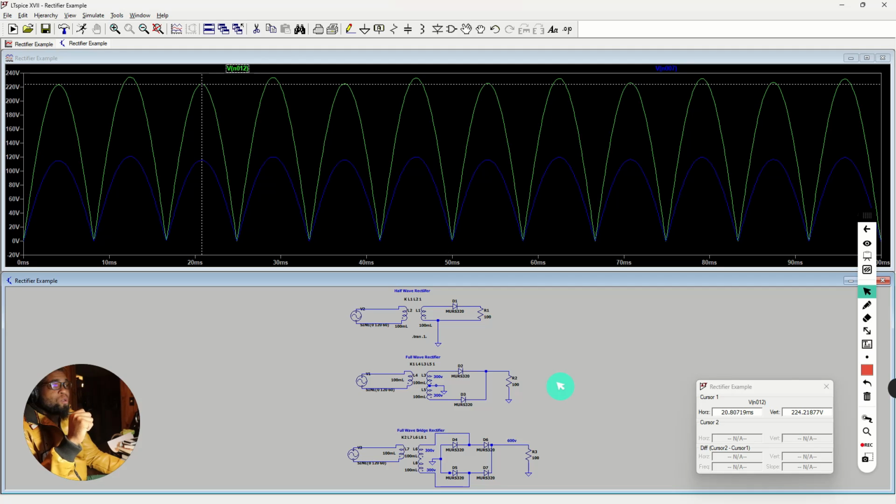I'll say a little more about this too. You'll start to understand this better when you get on the market and actually look at components. This is why I want to talk to you about this, because sometimes you won't find certain sizes of transformers, and you'll say, well, how do I get that voltage? How come I know that things are designed with 300 volts, but I don't find any 300 volt transformers? Because they're not using a 300 volt transformer. They're using a 600 volt transformer that's center tapped. Okay, you follow me? So that's one of the things you have to understand about this, right?